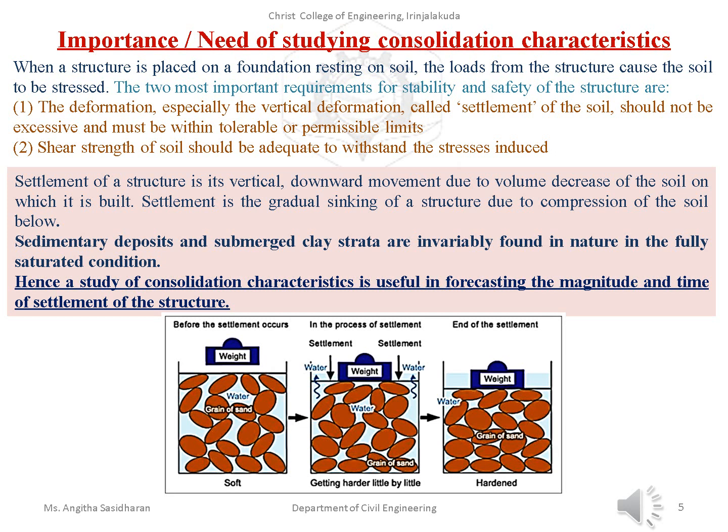And the grains here are different. Now they are getting closely packed. And after some more time, at the end of settlement, what happens? The settlement is more, much of the water has escaped out of the soil, and the sand grains have very close packing and it is getting hardened. So this is how settlement is happening. If you want to know whether any structure is likely to have a large settlement after construction, we should study the consolidation properties of the soil over which the building is made.